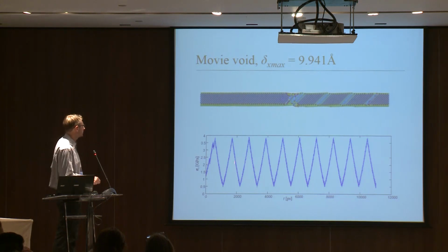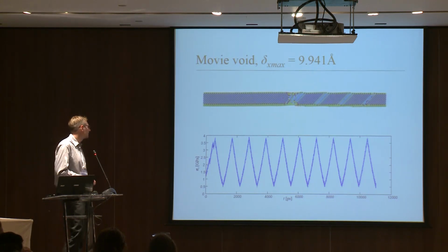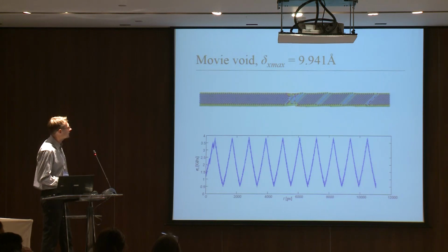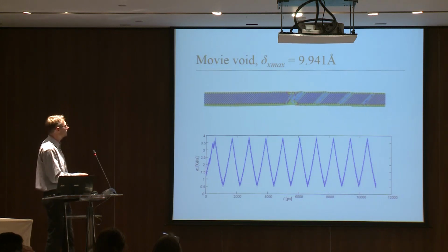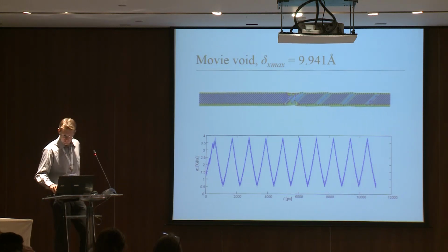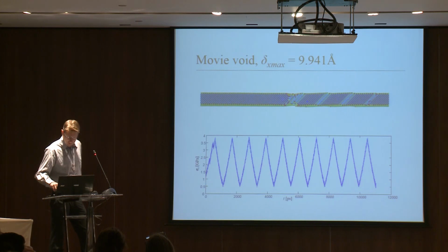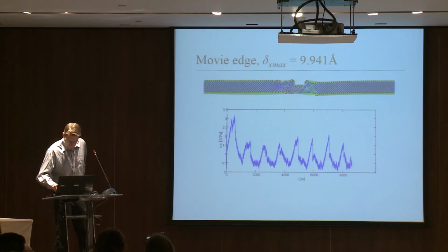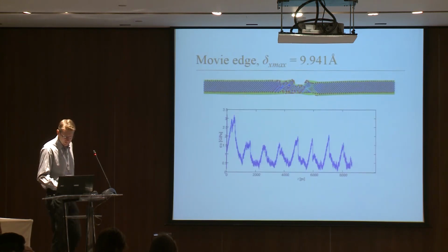And that's also seen in these stress versus time plots, that nothing more happens. So in this case, no more damage happens. So we would expect infinite life after this first plasticity. Oh. And that's the last one.